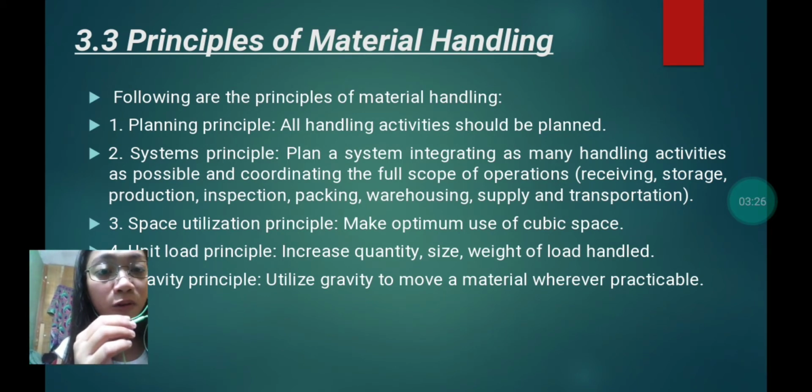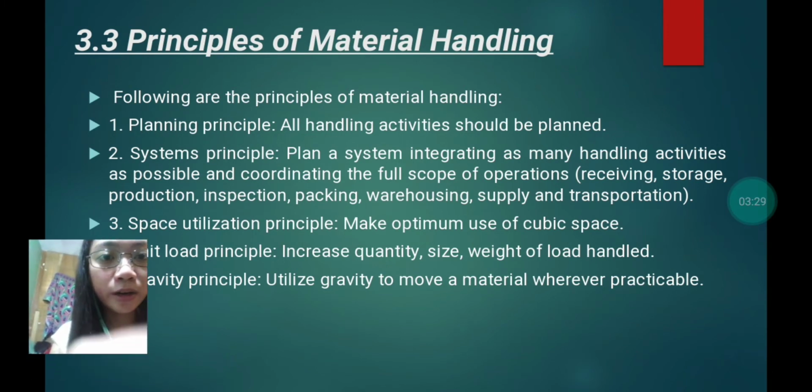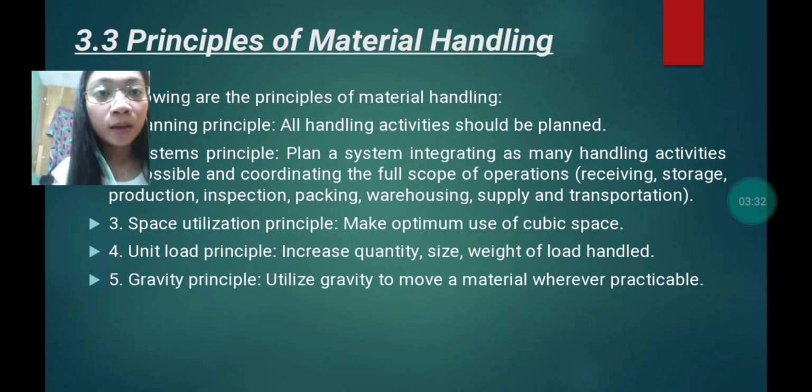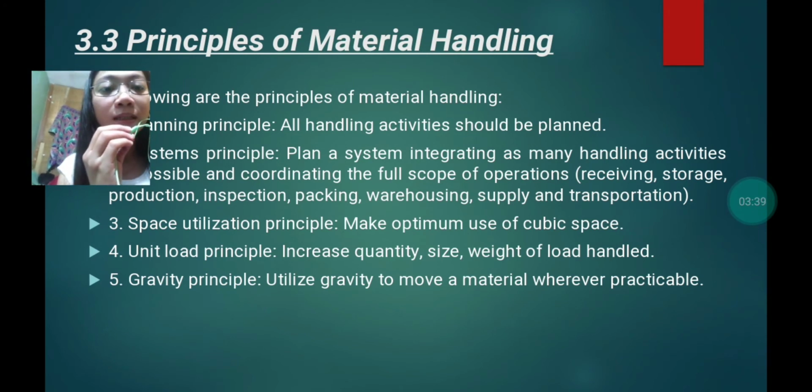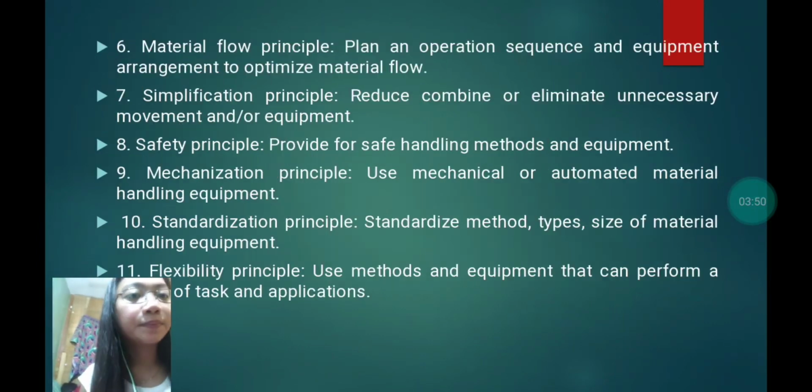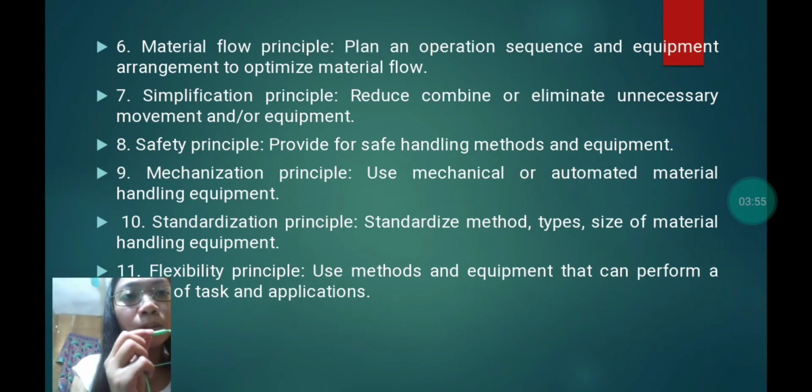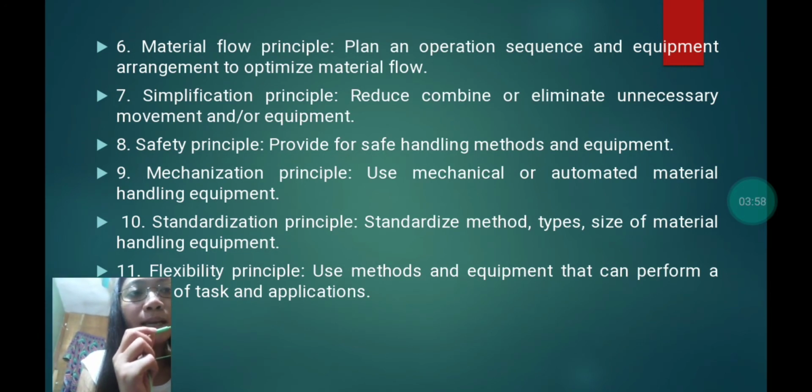And fourth, we have unit load principle. Increase quantity, size, weight of the load handled. And fifth, gravity principle. Utilize gravity to move the material wherever practicable. And this is the continuation of principles. 6, material flow principle. Plan an operation sequence and equipment arrangement to optimize material flow.